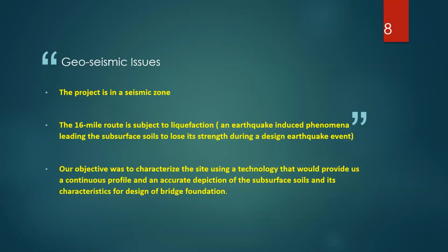So as I'm sure you can understand, the gravity of this with respect to the bridge foundation design and also the objective of this investigation and CPT was to basically provide a continuous profile, right? And that's what CPT does. Unlike your borings, where you don't have a continuous profiling of your subsurface characterization, CPT has this excellent capability to do exactly that, a continuous profile, and basically an accurate depiction of your subsurface soils.